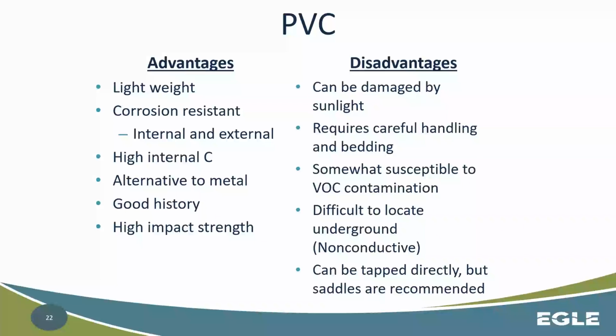So if you're leaving it out for a long time, over summer, because you had it for a watermain project, you bought a whole bunch of it, and there's some left over, there's that potential it could break down and deteriorate. Okay, because it's just plastic. Plastics break down, especially with sunlight and temperature and time and everything else, right? So it requires careful handling and bedding. Again, it can have stress fractures and things like that. So make sure you're handling it properly, not damaging it in certain ways.